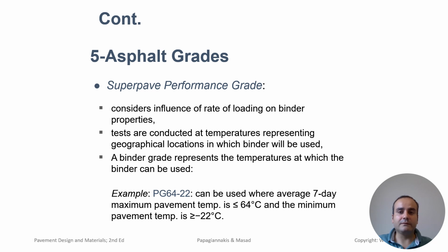the pavement will carry. By accounting for both temperature and loading, the PG system provides a much more accurate method of selecting binders that will last longer and perform better under real-world conditions.